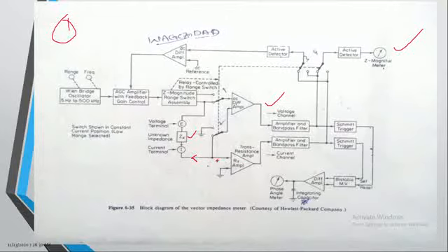So here we are having the input current. This input current is converted into the voltage form, and it is passing through the band pass filter, and we are selecting a particular element. Using the band pass filter we are selecting a band of frequencies. This voltage is given as an input to the active detector. Again, one more active detector. Remember that the output of this element is given as an input to the Z magnitude. Output of this element is given as an input to another one, which is a DC differential amplifier.